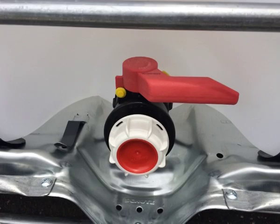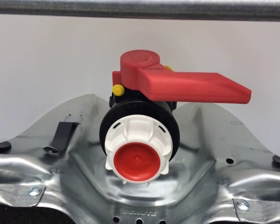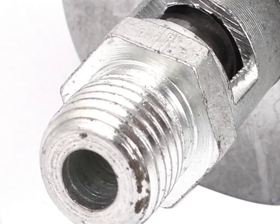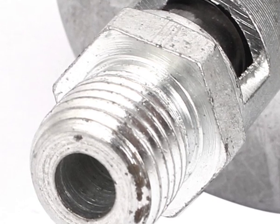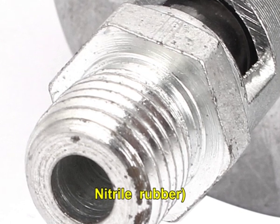Valve cup. This is mounted on the valve housing, into which fits the valve stem itself, usually formed in tin plate, and incorporates a grommet or flowed-in compound lining, usually nitrile rubber, to ensure a leak proof seal with the cone.